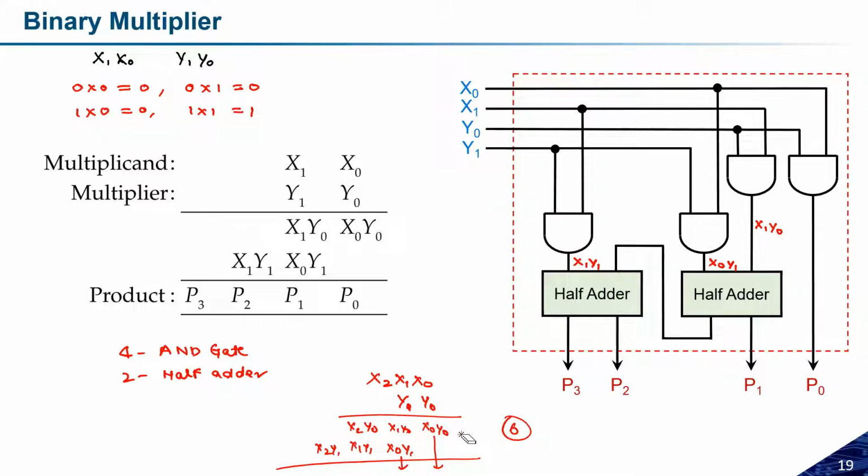And if we talk about the half adder, so let us see how many half adders are needed. So this will be reflected as it is. This is what we will add. Because there is no previous carry, so half adder will be sufficient for this purpose. Now one carry will be generated that will come over here. So for this purpose, you need one full adder. So 2 terms are already there and one carry will come. So one full adder will be required for this purpose.